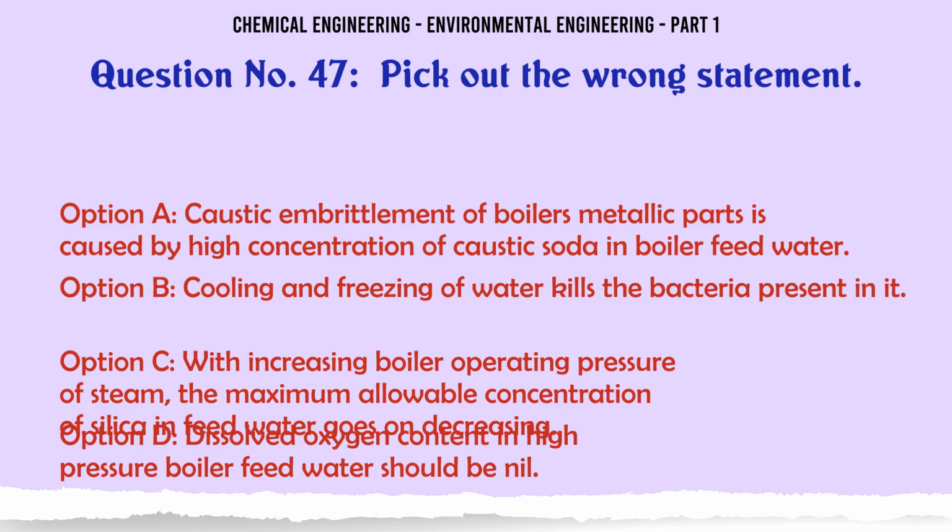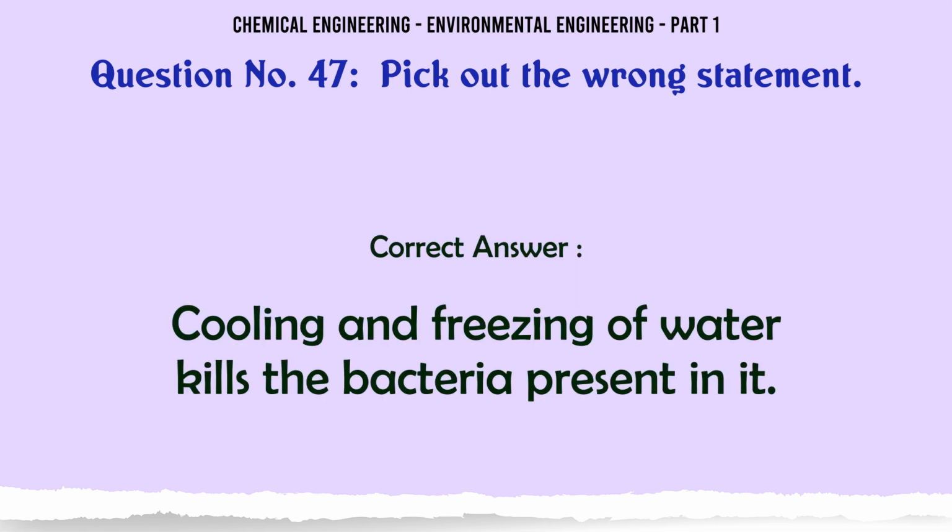B. Cooling and freezing of water kills the bacteria present in it. C. With increasing boiler operating pressure of steam, the maximum allowable concentration of silica in feed water goes on decreasing. D. Dissolved oxygen content in high-pressure boiler feed water should be nil. The correct answer is cooling and freezing of water kills the bacteria present in it.